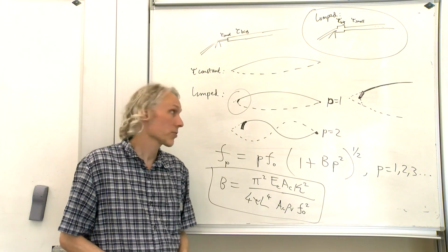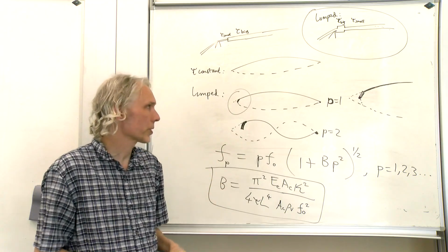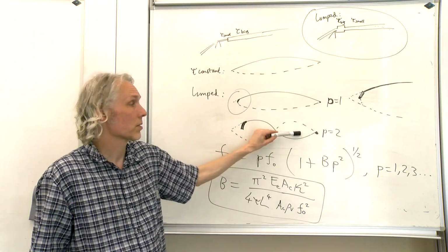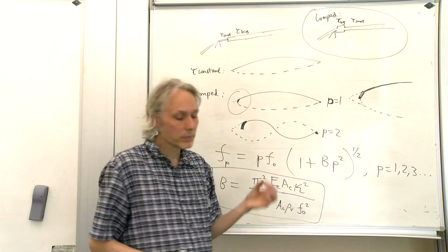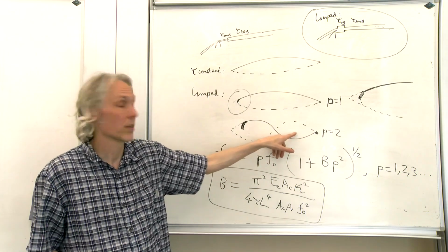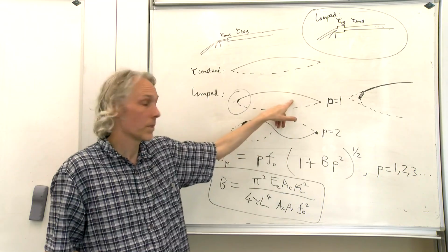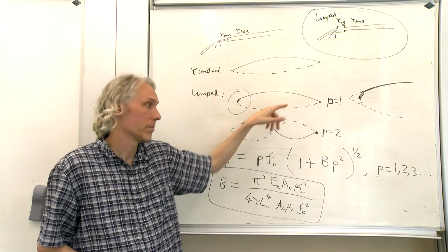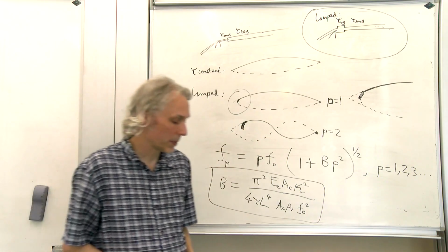So when I'm designing my strings, I design lumps on my bass strings so that the second harmonic, even when you're playing up at the 21st fret, the second mode is a true 2 times the fundamental, instead of being sharper than that. So that's what the lumps are all about.